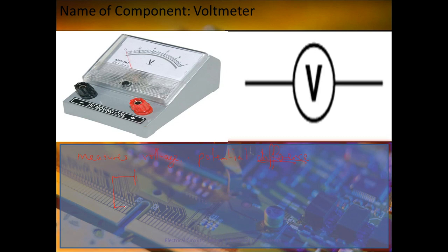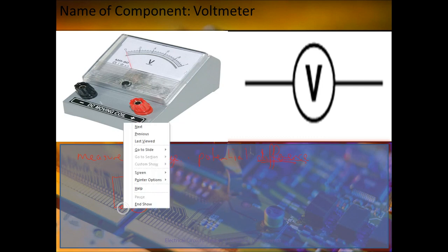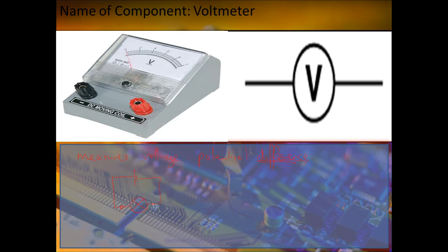If we had our bulb and we wanted to know how much voltage it was using, we would need to examine the electrons before they enter the bulb, and we'd need to re-examine those electrons once they have left the bulb. So our voltmeter would need to be connected to both sides of that bulb. And that's a term we call in parallel. By doing that, we can measure the potential that the electrons have there. So we get a value for the voltage before the bulb, a value for the voltage after the bulb, and the voltmeter would display the difference.